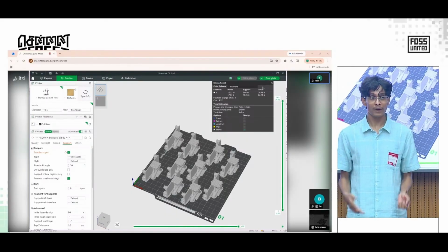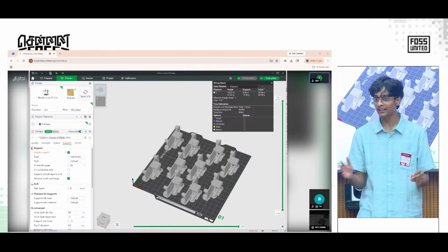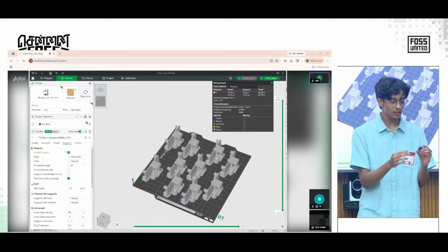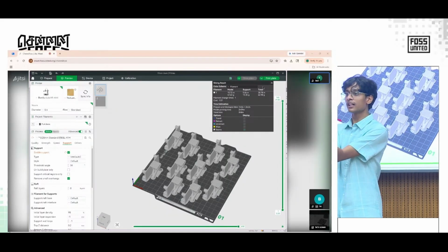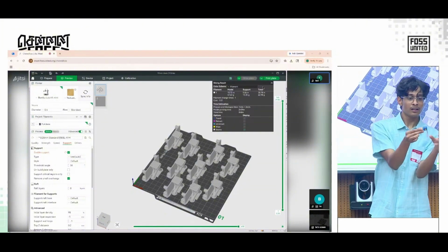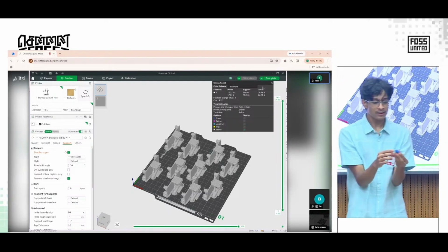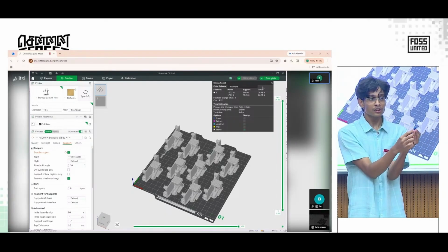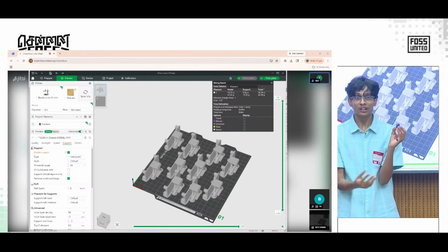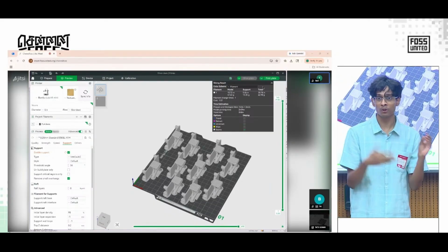But adding a motor driver makes things very complex. We need more wiring and it increases the size. That's why we use a modified servo motor. If you can see inside, this green chip is what actually controls the servo motor, and this is the motor. There is a potentiometer here. When it moves, the resistance changes, and according to the resistance, the microcontroller knows what position to set.